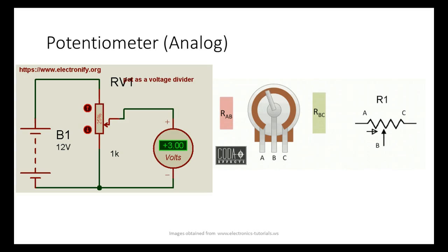A potentiometer gives us a voltage that's proportional to wherever that thing's at. So if I had 10 volts across A and C, this would give me something between 10 and 0. If it's 5 volts and it's 360 degrees, it says I'm at 180 degrees, or I've moved so far. So 5 volts might mean it's moved 6 inches, and if I measure 10 volts, it would mean it's moved 10 inches, right? You understand that?